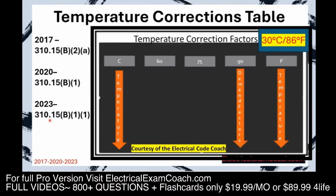Go ahead and head to your code cycles table number now. Pause the video if you need to. When we get to the table, we want to verify we're in the right table. And how we do that is make sure that we're in the table that says 86 degrees Fahrenheit. We do not want to be in the table that says 104 degrees Fahrenheit. The table looks identical, but it'll have all the wrong numbers that you need. So you want to make sure that you're in the table that says 86 degrees Fahrenheit. Then if you're able to in your state, I want you to highlight that table. Just highlight the title of it. So when you're flipping through and doing these questions, you're going to know that you're in the right table and you don't have to second guess yourself.